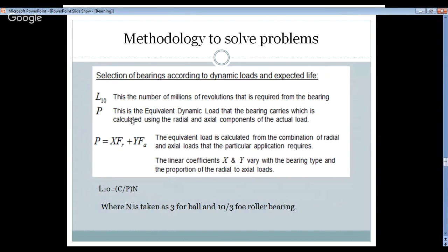As manufacturers suggest in their catalog, they have opted only for 90% reliability criteria, so we fix our value as 0.9 for reliability. If we have to convert this reliability term for a lesser or higher value, the selection criteria may be different.